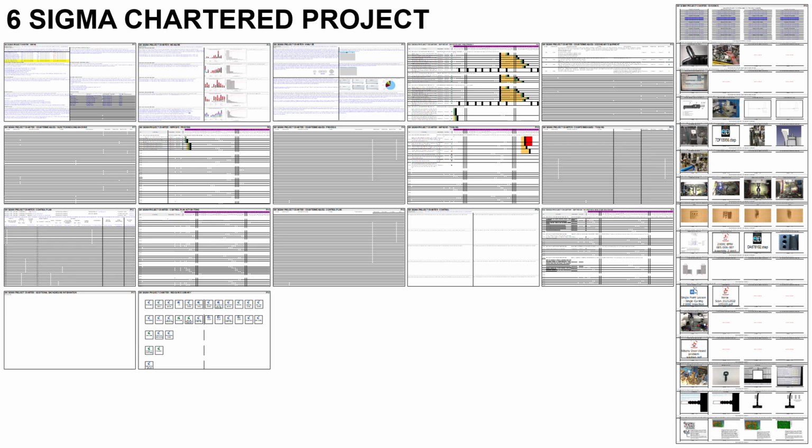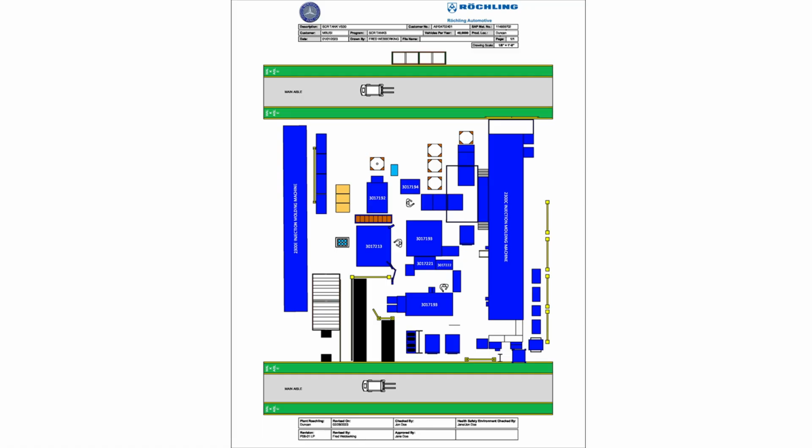Mean time between failure was 2.4 hours and the mean time to repair was 4.4. What I was able to calculate was that the true availability was 70% and the raw throughput yield was 78%. This is the layout of the production cell that had 8 discrete processing operations, and this is why I chose to use raw throughput yield and availability as my Y output key performance indicators.